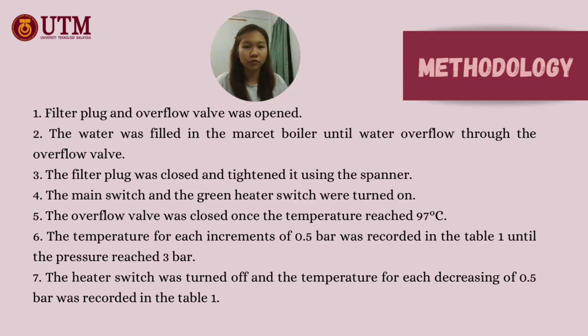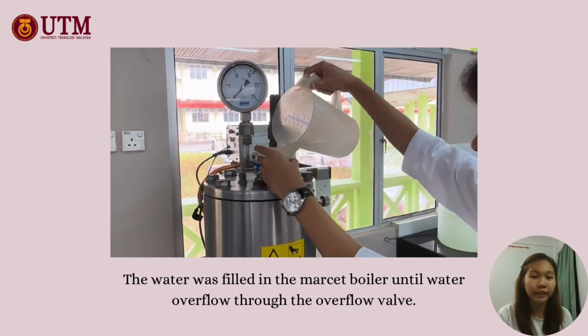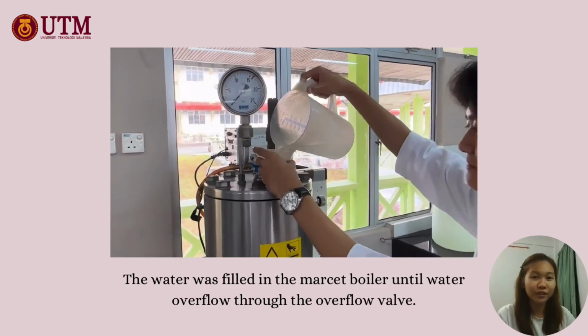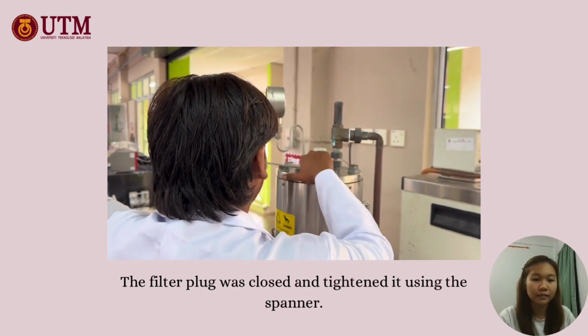So this one is the overall methodology, and for the next slide I will talk about this methodology together with the video of our experiment last week. After the overflow valve and the filter plug were opened, the water was filled in the Marcet boiler until water overflowed through the overflow valve. Then, the filter plug was closed and tightened using the spanner.